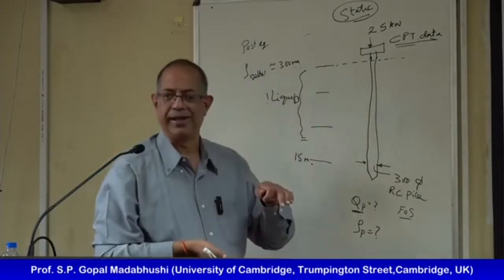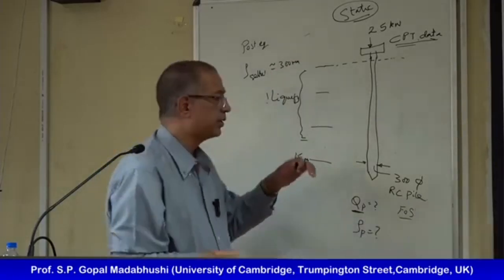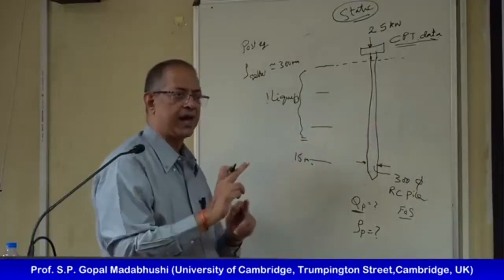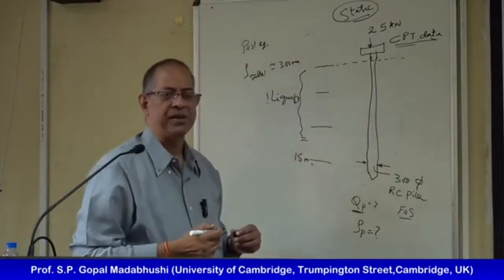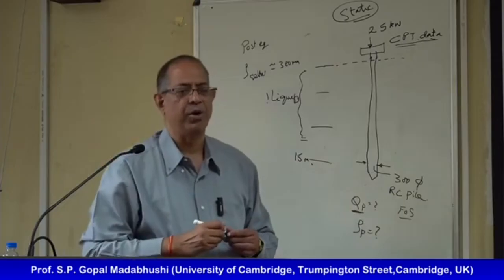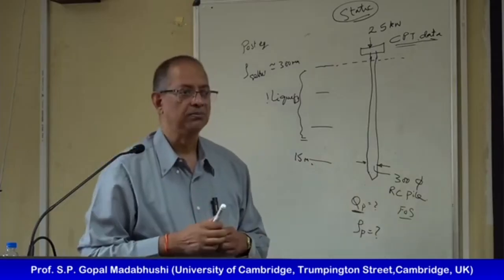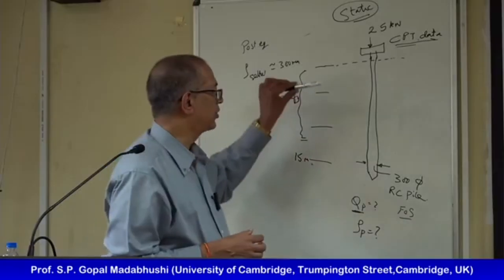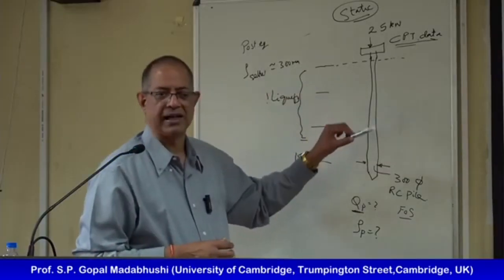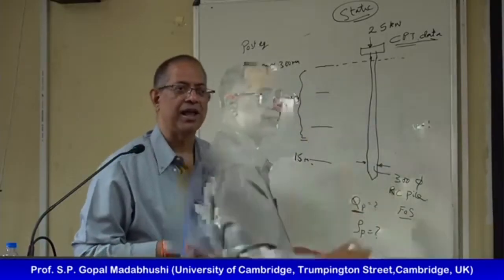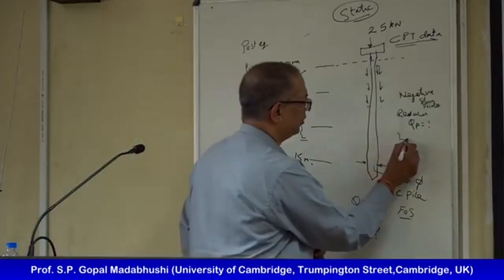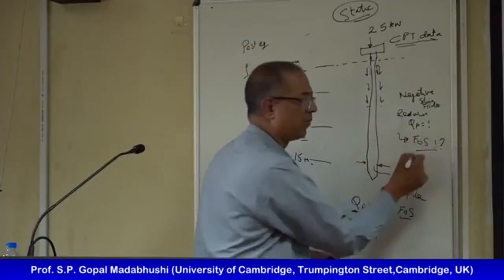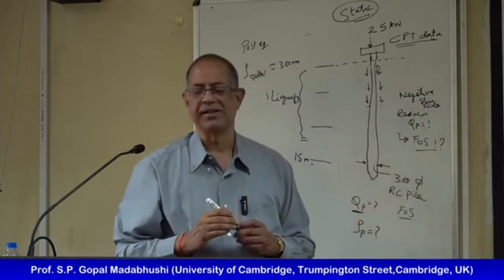The soil itself is going to settle, but the pile is going to stand proud. If that happens, what extra load will come onto the pile? The soil wants to settle, the pile doesn't want to settle. So what is the new factor of safety? Do you understand the problem?